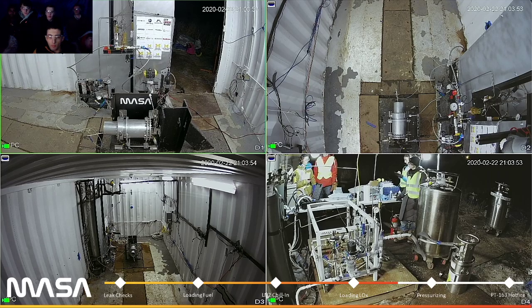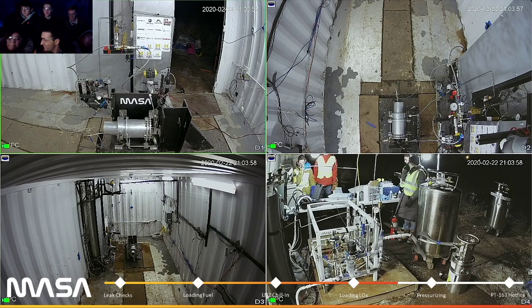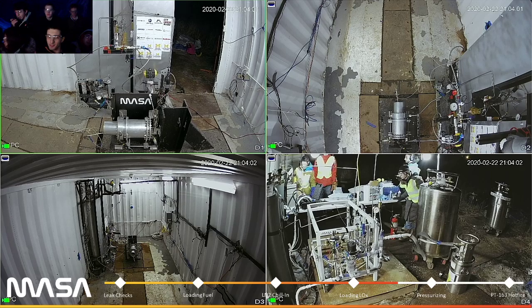Oh yes, Ethan's right. It's actually mostly limited by the size of your vent valve, which is why we have a massive vent valve. In fact, the vent valve is as big as the main propellant valve. The main liquid oxygen valve. Yeah, they're the same size. Target for pre-fill.